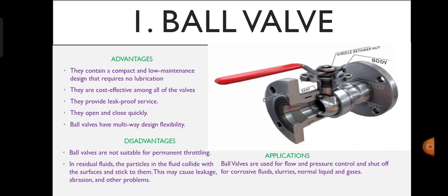The advantages of ball valve are that they have a compact and low maintenance design that requires no lubrication. So one major advantage is that this valve does not require too much maintenance. They are cost effective among all the valves. They provide leak proof service. They open and close quickly. Ball valves have multi way design flexibility. So these are the advantages of ball valve.